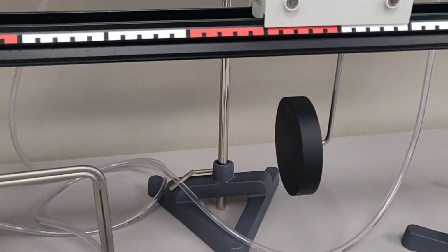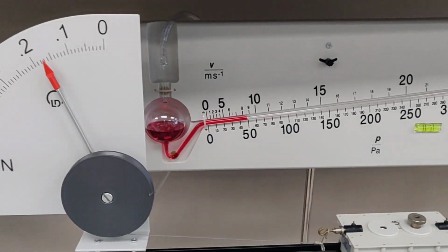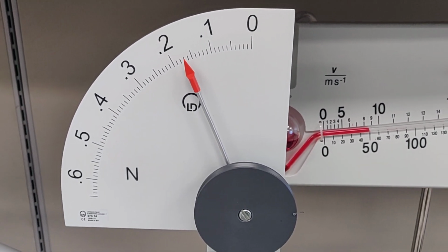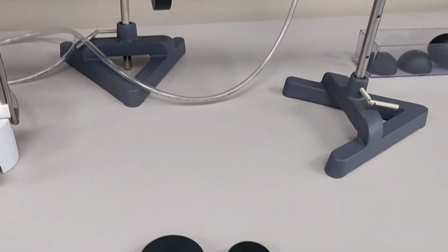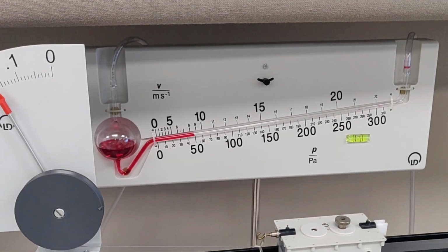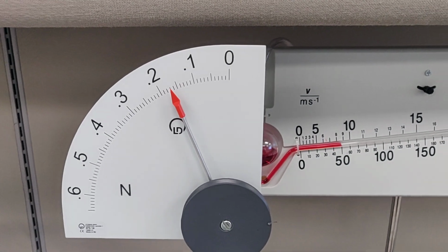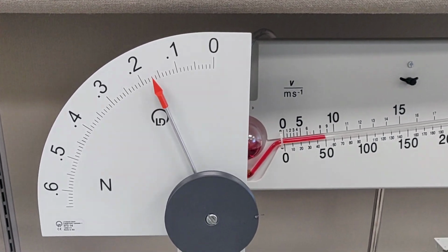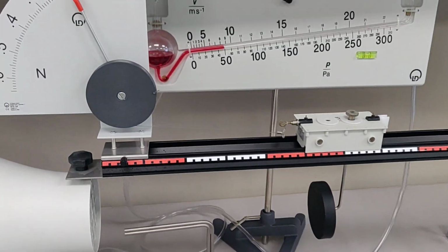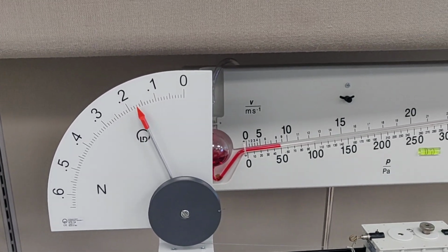Next you will remove this disc and put the other medium diameter disc in there, and pressure will be same, velocity will be same, the drag force will change. You get F2. Then you will remove that, put the smallest diameter disc in here, and pressure is same, velocity is same, you will get F1. So F1 is for the small disc, F2 is the medium disc, F3 is for the biggest diameter disc. One by one you will remove these discs and plug in the other one, and keep reading the drag forces. Okay, that completes your test number 1.